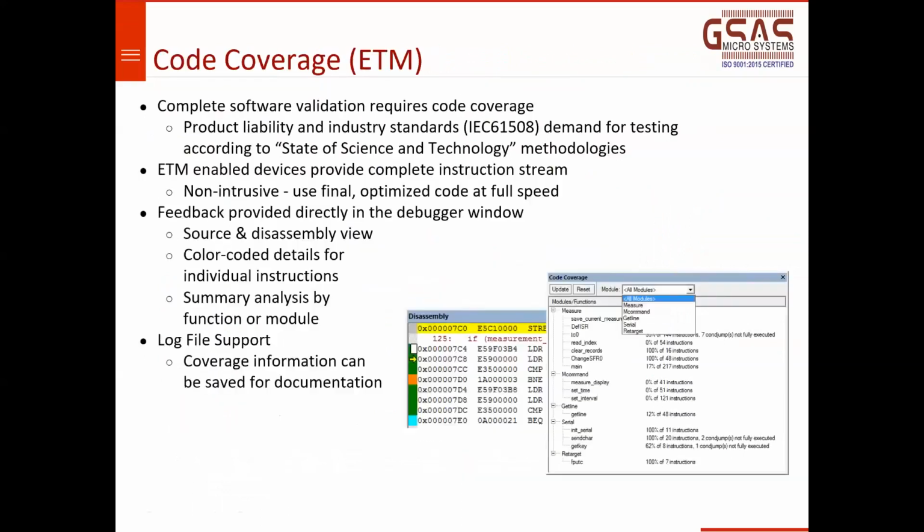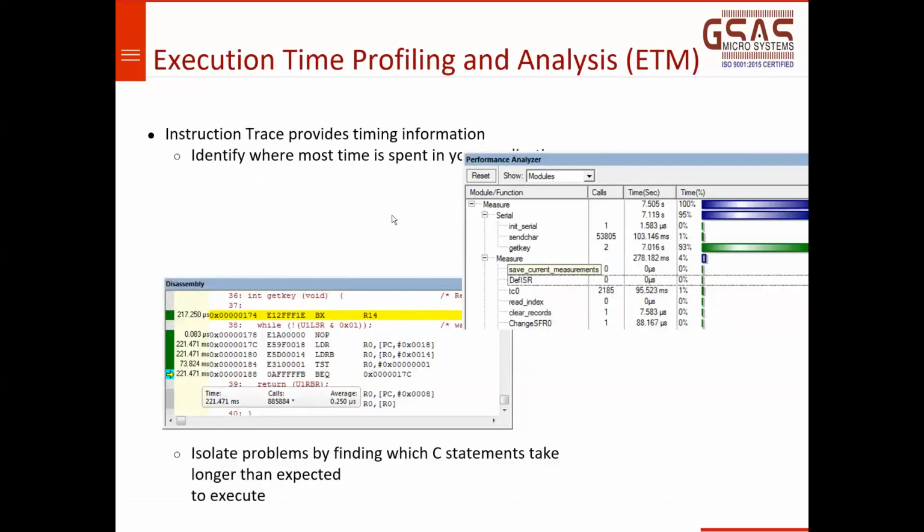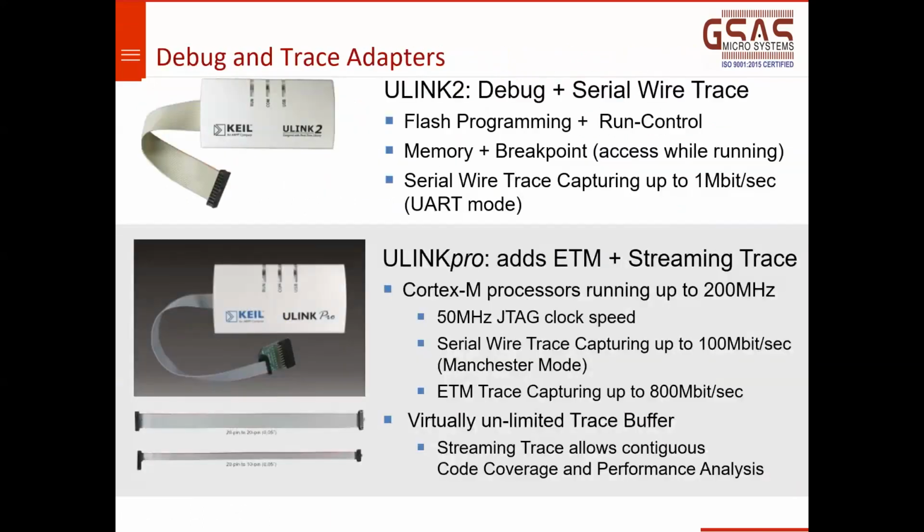execution profiling. Yeah, here it is. It's here only, execution profiling. Execution profiling will tell you the time taken for every C statement or every assembly instruction. You'll get this as part of your real-time ETM trace collection. So what all you get? You get performance analysis, you get execution profiling, you get code coverage.